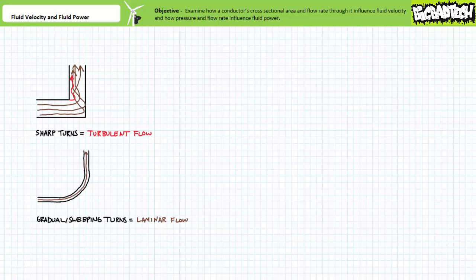Realize even in the most ideal of laminar flow conditions, isolated pockets of turbulence will always develop at the inevitable turn, restriction, kink, bend, fitting, or valve passage. Going back to my earlier depiction of flow as individual particles, each having their own velocity, it is for very obvious reasons turns are most efficient when they perform gradual sweeping bends. Any particle with a characteristic inertia negotiating a sharp turn or obstruction would slam into the corner and bounce around the bend, contributing to turbulence and inefficient operation of the system.